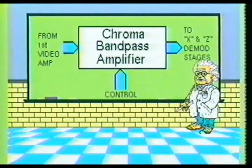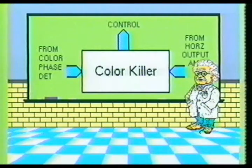The primary function of the chroma bandpass amplifier is to separate the chrominance information from the composite video signal. It also amplifies the color information. The color killer stage is used to control the operation of the chroma bandpass amplifier section. The color killer has the ability to turn the bandpass amplifier on or off.